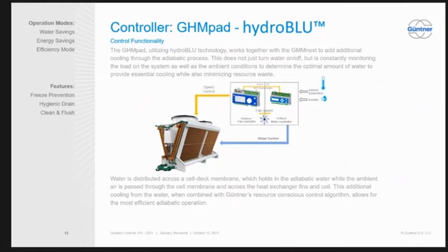Right here we have our GHM controller. On the left, we have our GMM, and on the right, we have our GHM. GMM stands for Guntner Motor Management. GHM stands for Guntner Hydro Management. The way these work together is the GMM will control the fans and ramp them up and down. The GHM looks at the ambient temperature, the ambient humidity, and the fan speed the GMM tells it, and it'll determine how much water to put across the pads.